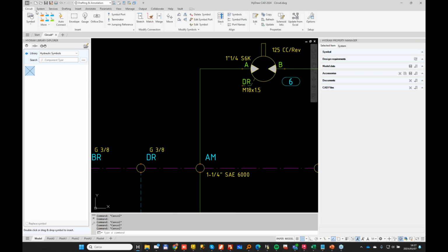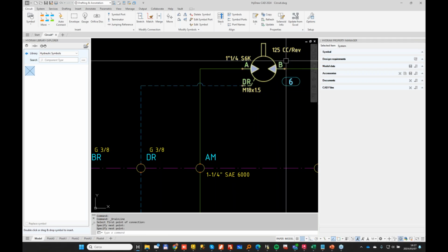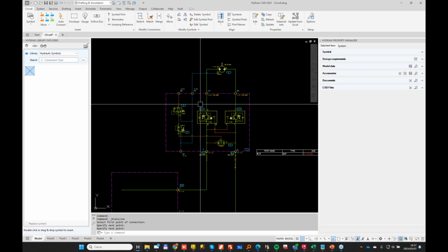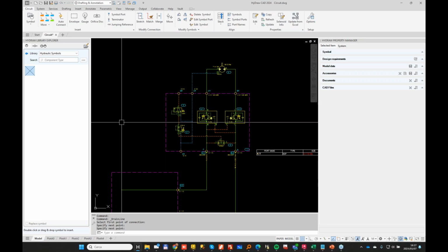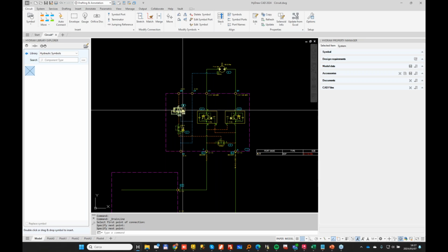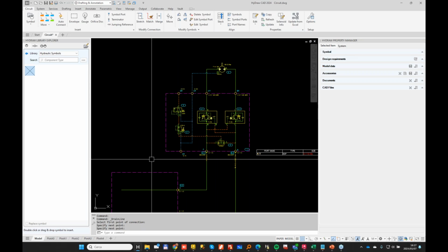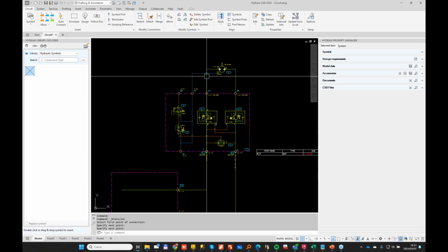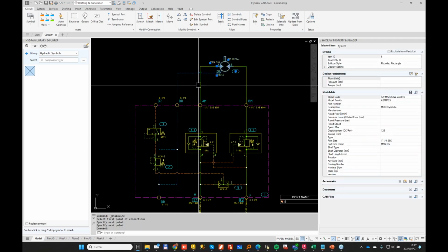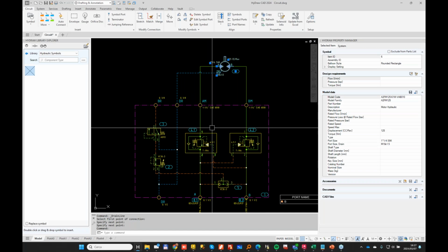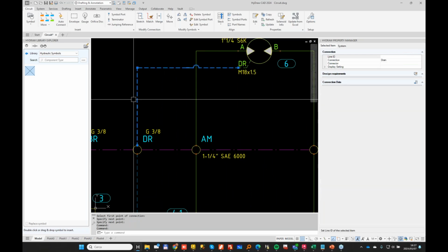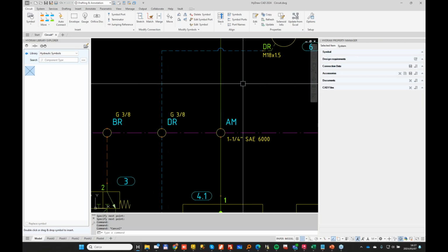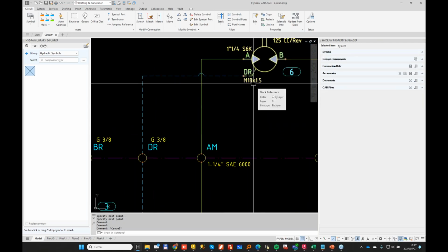I want to make the drain line. So the motor, and in a month we'll have an MD Tools webinar showing how to design a manifold mounted to a hydraulic motor. I'll probably use this case as a small example. So basically I have a motor which is flanged to the manifold, well, a manifold flanged to the motor, and the drain will be connected through a tube to a drain port. So here we have two different port sizes.